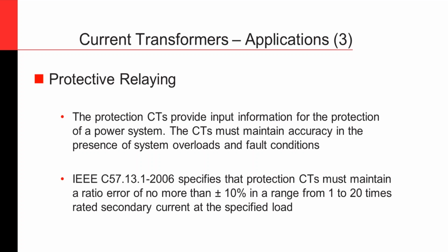That can be used in your load flow analysis, whether your system is stable or not stable, whether you want to isolate a system because it is unstable, and what kind of system you have to isolate. So you're completely monitoring your power system based on the readings from your CTs and the PTs. For me, this is one of the major sensors of your power system as such. And one main application of the CT, as I told you before, is metering, and the other thing is protection.